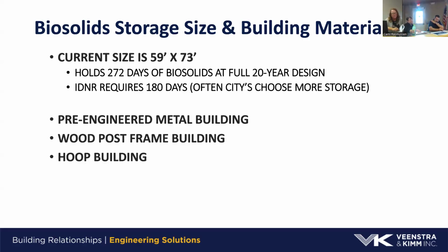So right now, if you had 270 days of storage at that full design, take that times 3, and that's about how many days of storage you have. So it's a lot of storage. DNR does require us to have 180 days of storage at the full design, but certainly what we're showing right now is 100 days more. I've yet to be to a facility that complains they have too much storage, but we just wanted to present this as an option. We could look at downsizing this building.